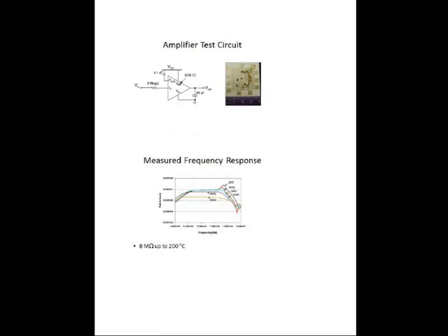The way to test it is with this test circuit. Since this amplifier is non-inverting, a positive amplifier, even a very small input grows and creates oscillations. Even if you don't put any capacitor there, with the DIP package, we observed spurious oscillations. So we ended up creating a gold ceramic type of board, placed our die here, and placed an 82 picofarad load capacitor to cut down the oscillations.